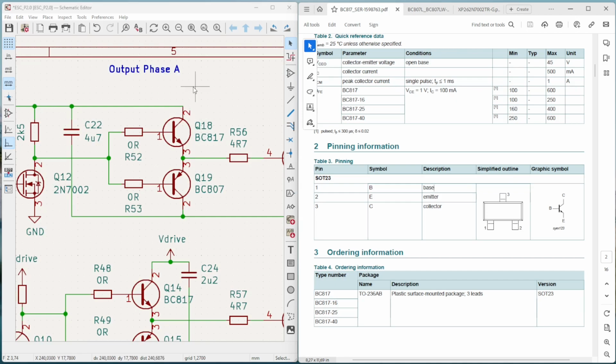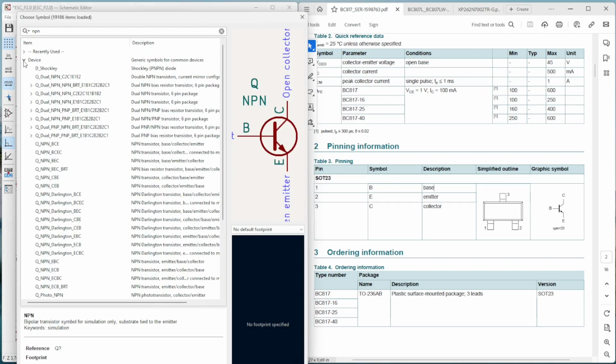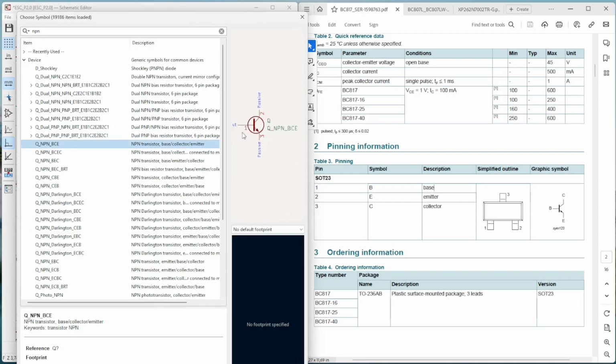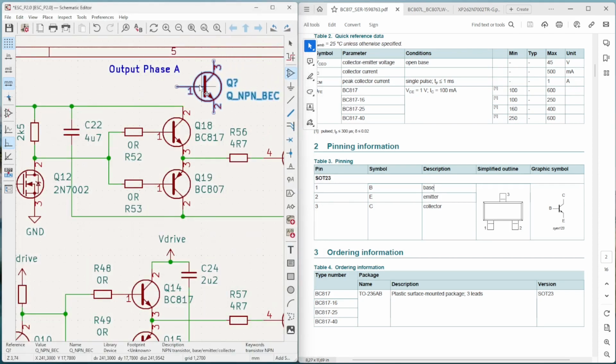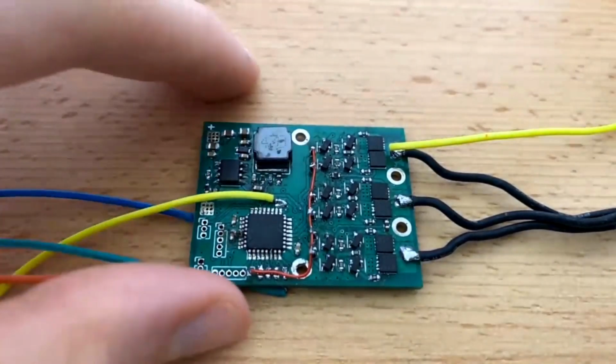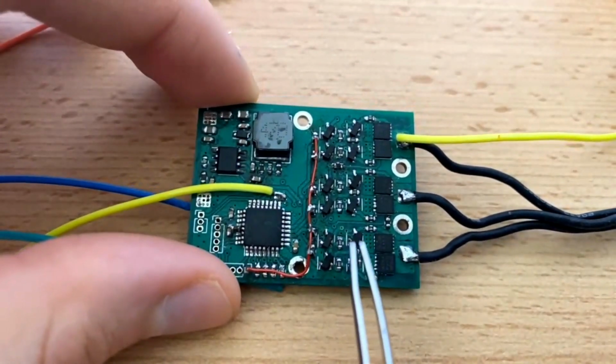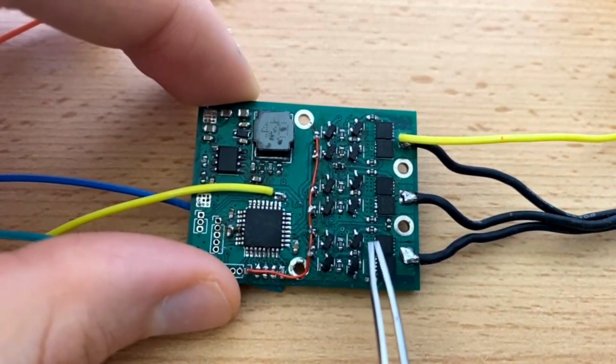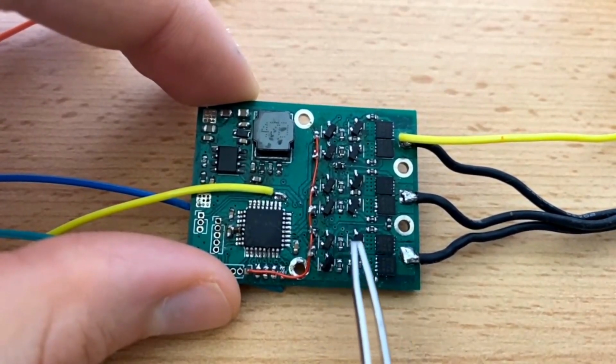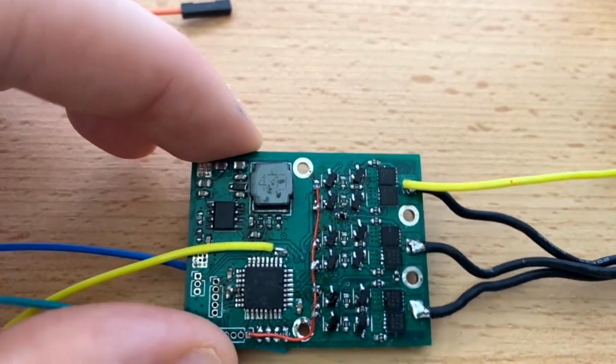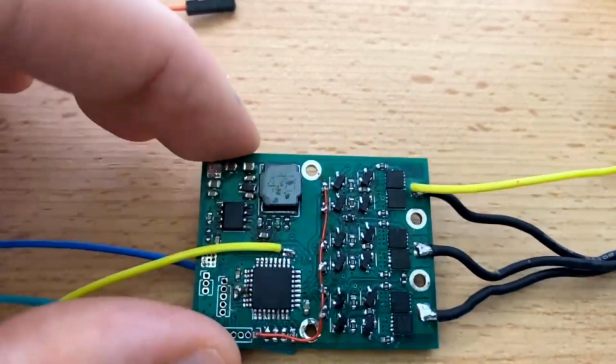So when you select the component in KiCad, I unfortunately selected base 1, collector 2, emitter 3. And I would have needed, according to the components I used in the end, the base 1, emitter 2 and collector 3. So I should have used this component instead of that. To get it working anyways, I flipped the components, bent the legs down and rotated them to solder them still on the proper spot. Like this, I got the gate driver working and it works as intended.